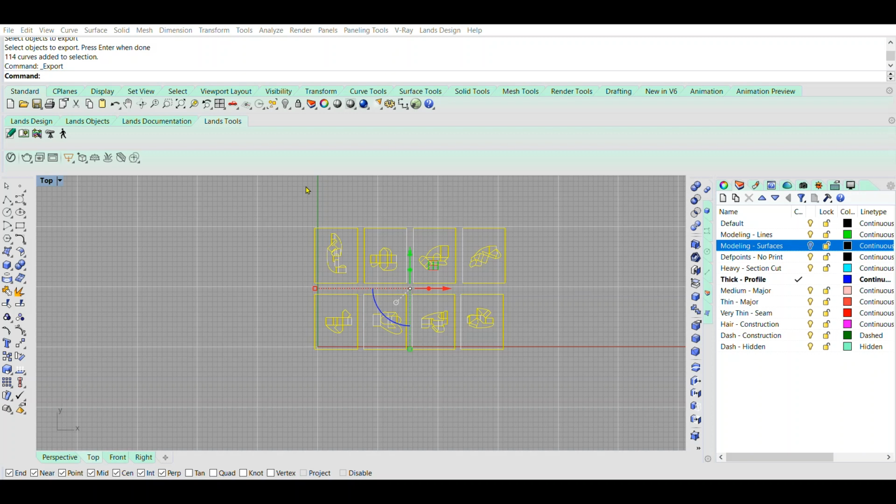And then I already have one of the examples I had here. So module 1 export, I'll just name that one part 2. And then options, there's 2004 polylines or 2007, whichever one. A lot of times those tend to be the best way to preserve the joined lines created in Rhino and your layers.